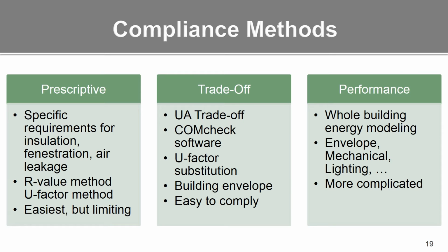And as far as the insulation, it gives you the option to use the insulation R value method, where it outlines specific R values and how many layers of insulation and types of insulation to use. Or it gives you more flexibility with the U factor method. And we'll get into that in part 2 and part 3 of the webinar series.